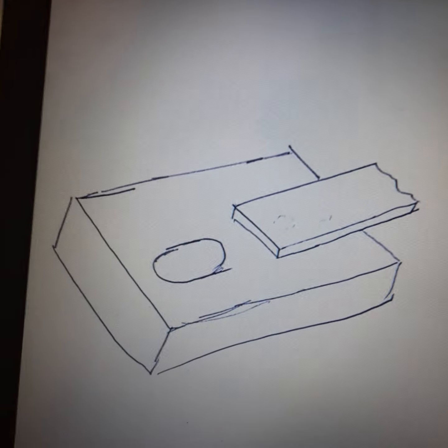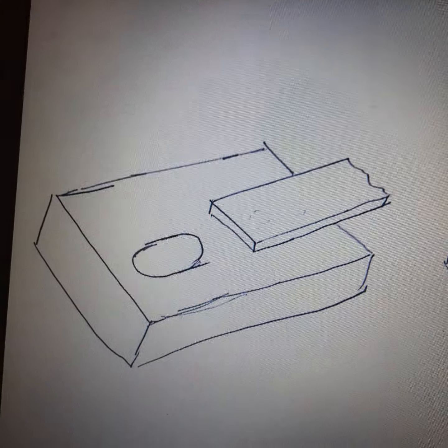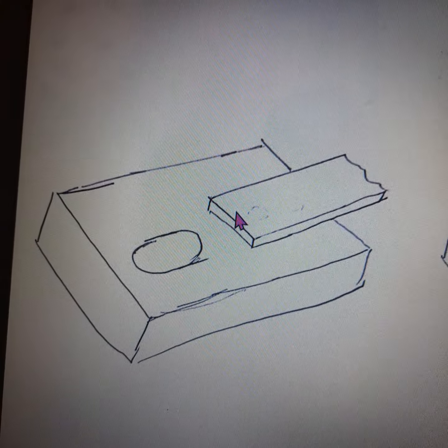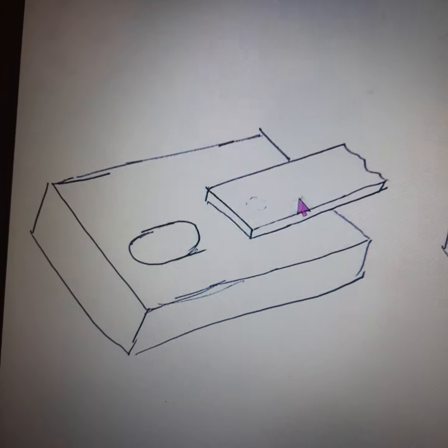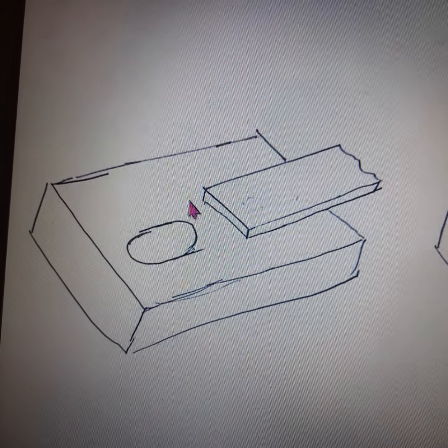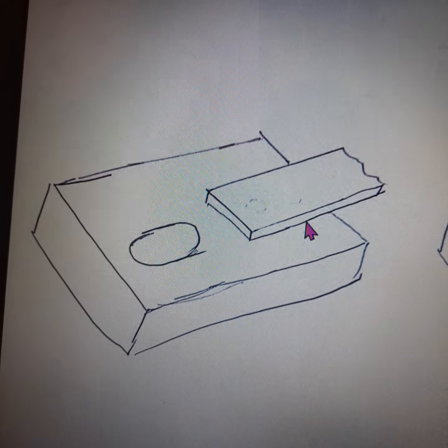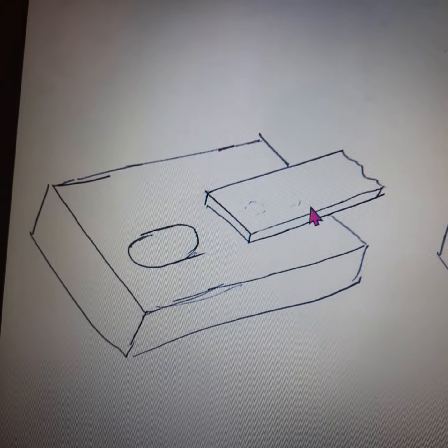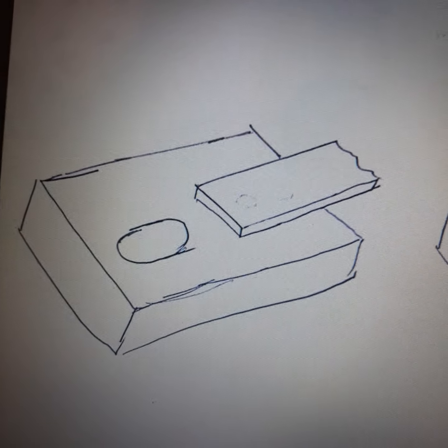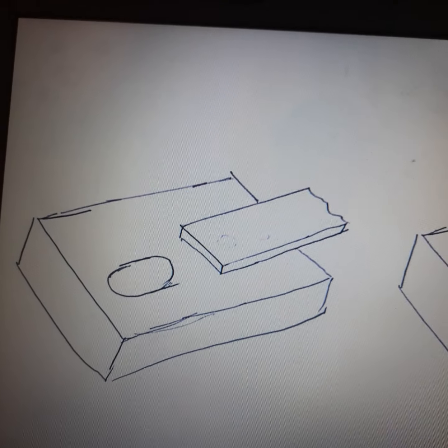Before the first stroke is initiated, we have to keep the feed strip. This is the feed strip. The feed strip is the raw material for making the sheet metal product. The feed strip is placed up to this point. It can be in the form of a continuous roll, or in the form of long strips.